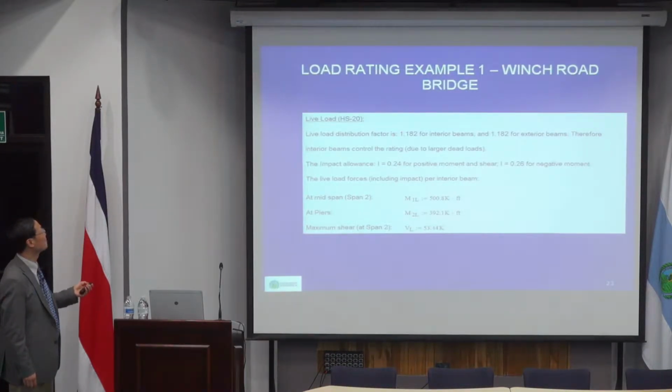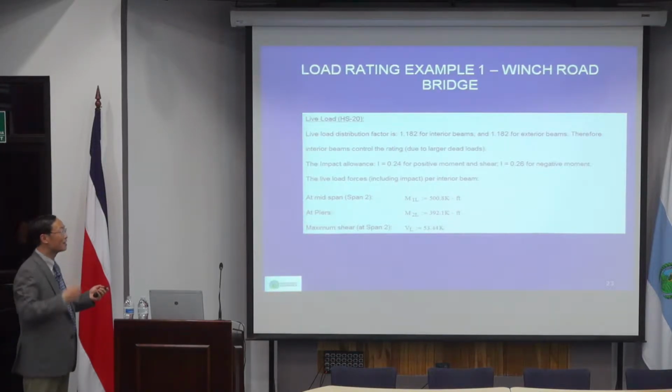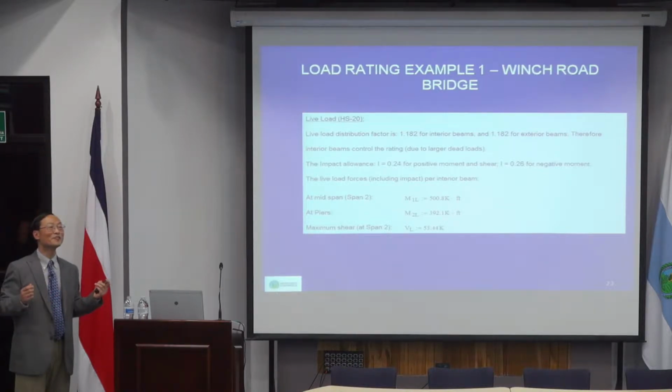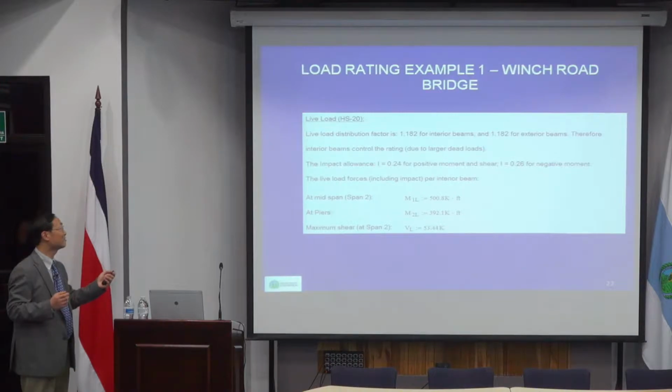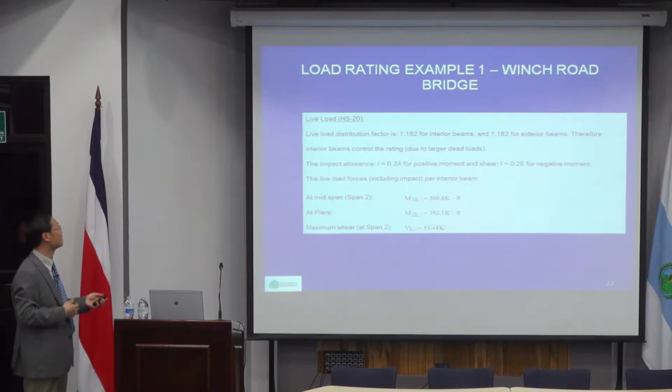And live load. That bridge was rated for HS20. HS20 is the exact same live load configuration as HL93. HL93 is HS20 plus a uniform distributed load combined. So it's much heavier than HS20.